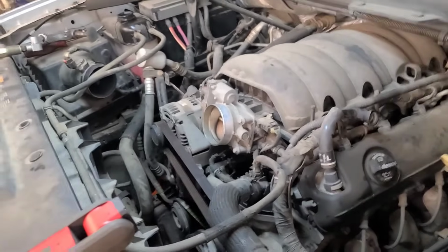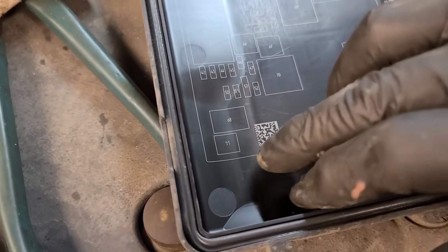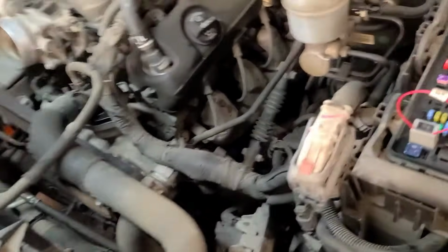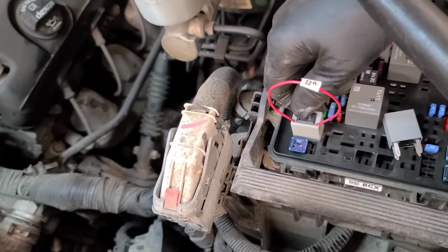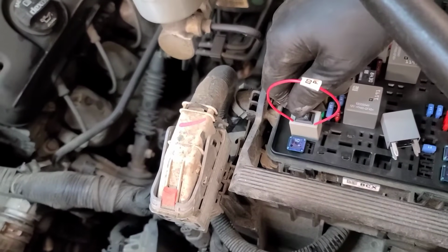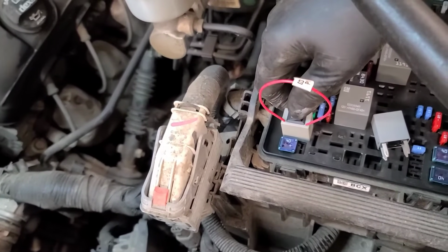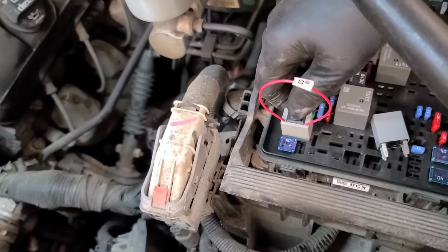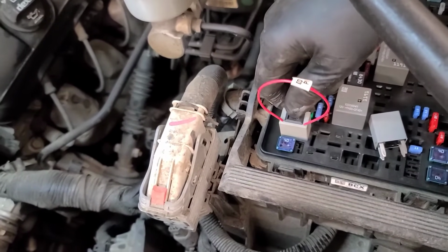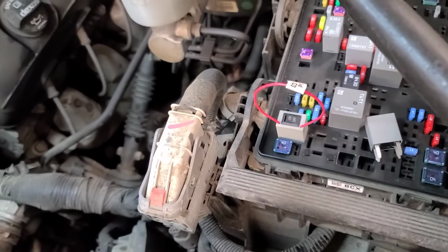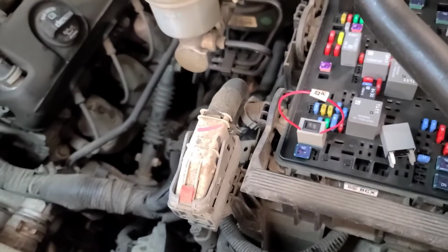And to do that, I've removed the starter relay. Starter relay is number 68 in the fuse panel here, this one right here. And I've got a starter relay switch in here, so when I rock the switch on, the engine will crank. So I'm just going to crank it for a few seconds to prime the oil system. Give the starter a chance to cool off. Do that a couple times, and then we'll hook up the air induction system and fire it up.